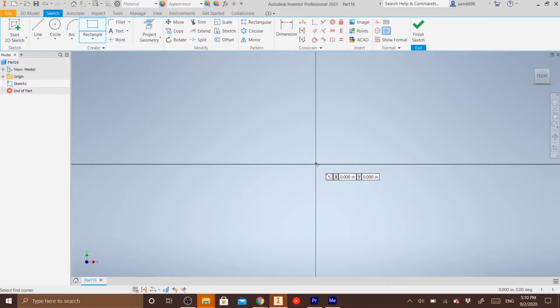If we're working with something that's probably going to be 3D printed, it makes a lot more sense to be adding on different features. But when we're working with something that we think we might machine using a CNC machine, removing features from a raw block of material, in my opinion, is the best way to go about it, because that incorporates your machining intent and makes it easier when you're actually working on creating the tool path and things like that.